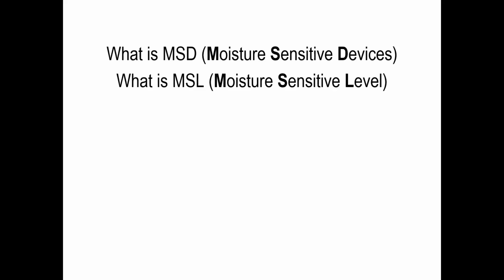And the sensitivity level is not given to PCBs, but it is given to components. And that's something that is defined by the component producer. And obviously every component producer wants to set a standard which you don't have to worry about, i.e. it doesn't matter how long the parts are outside of their protective packaging. However, if they set the specification too high or too low, that may have an impact on designers using the part in manufacture. So they need to be sensible, they need to do their own tests and qualify their parts to a certain level.